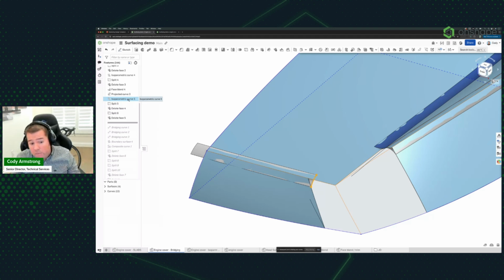And so one of the more common things that we see in surface modeling is, use a projected curve, project onto a surface, split using that projected curve, and then build on top of that split edge using a series of features. And really recommend avoiding that if possible. If you look at the resulting edge using a curve analysis, which I'll show you in just a moment, you'll see that they tend to create very messy, kind of not very clean resulting trimmed edges.